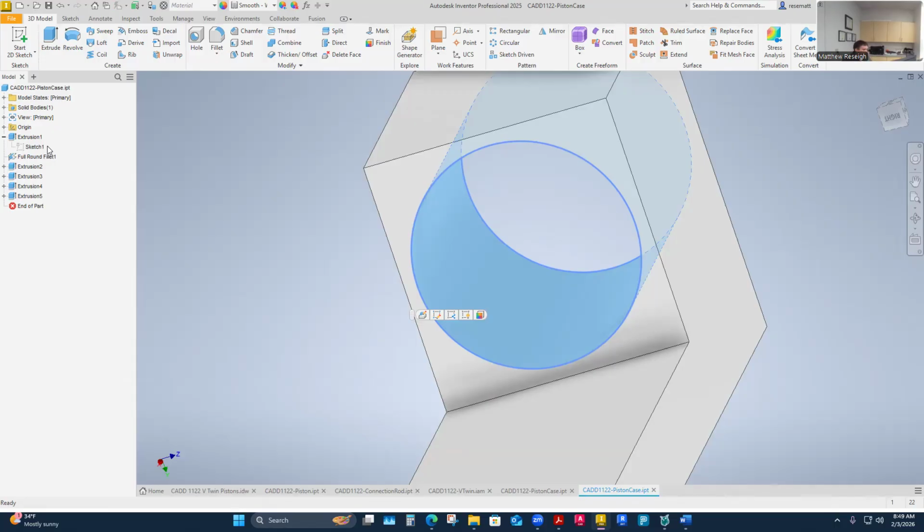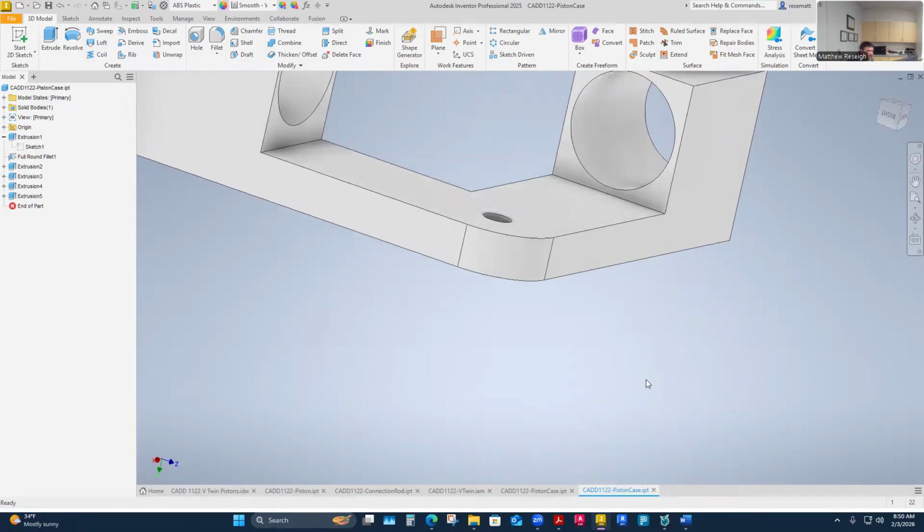And you are right. Nathan was telling me that sometimes if you go too sloppy, it actually doesn't make it work at all. It actually works better being just a little bit snug. It actually functions really well. It's a little harder to turn, but I can feel the tighter tolerances. Too sloppy a tolerance is not always your friend, because it lets your parts jam and get funny. They don't align right. And it was true. So a little bit of snug fitting was good.